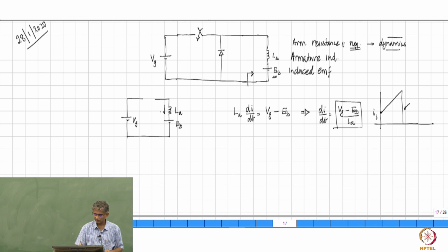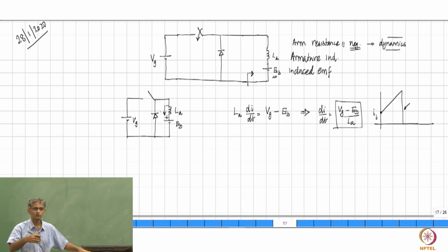If there was an inductor current flowing and you now switch this off, this inductor is trying to generate a voltage in this manner, and if you have a diode here, that attempt to generate a voltage in the negative direction will automatically switch on the diode, because the diode becomes now forward biased, right? Therefore, this diode will turn on, and a good semiconductor diode is as good as a short circuit,